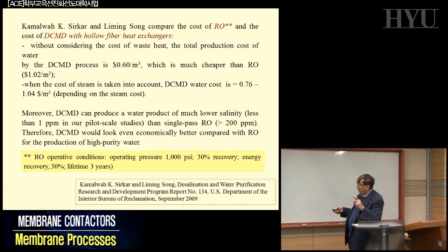I don't think that the reverse osmosis will disappear. Reverse osmosis will also be the most interesting process. However, reverse osmosis has some limits. Recovery factor 50%, because the concentration polarization phenomena cannot be totally avoided.